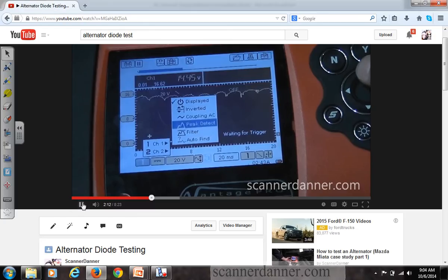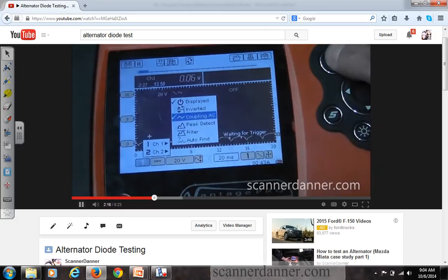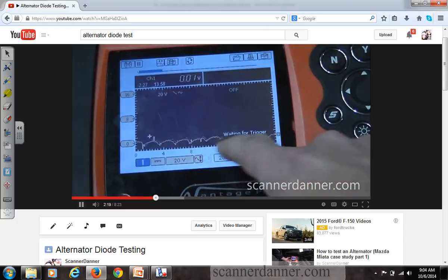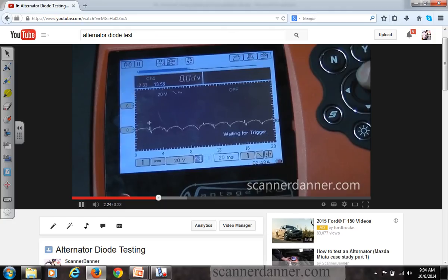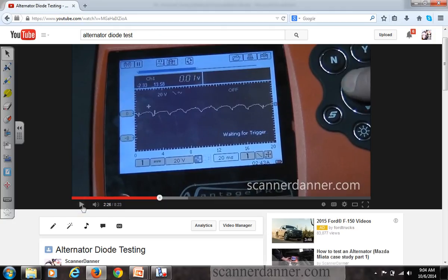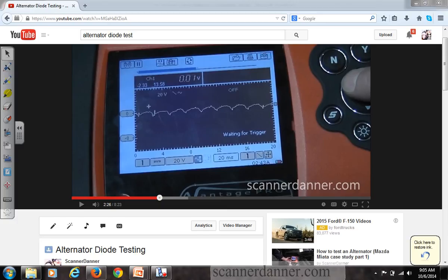Selecting channel 1, I'm going to AC couple it. And you'll see on the box that we just talked about with the straight line and the dots, just to the right of number 1 that's blue, you're going to see, oh, I thought I was incorrect. I thought that was going to change to some other symbol. It's not. I'm just AC coupling a DC setting. You see how I'm hovering around 0 now and I was up at 14? This is how you do it. Questions? Everybody comfortable with what we're looking at?